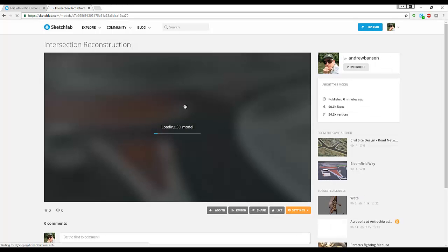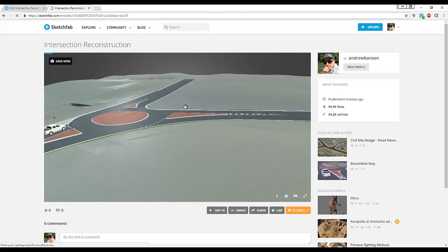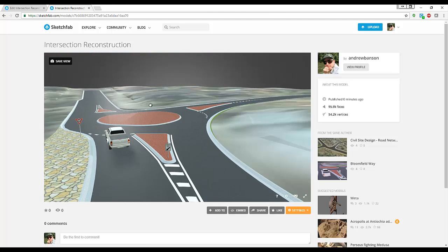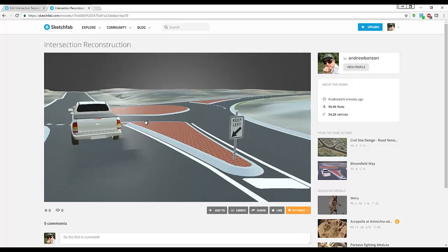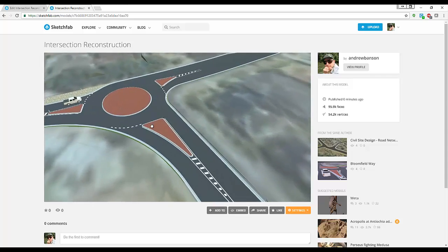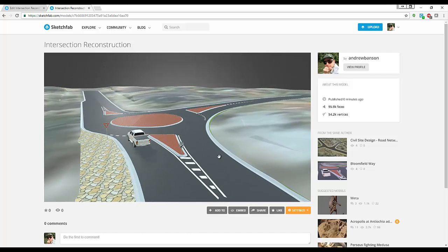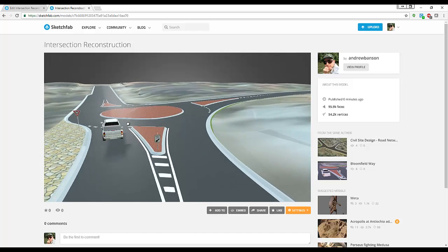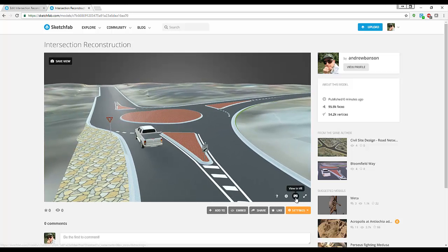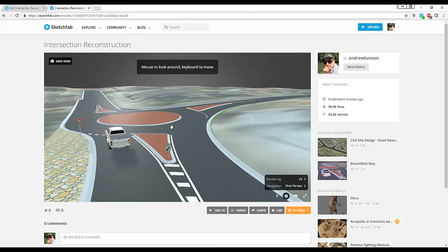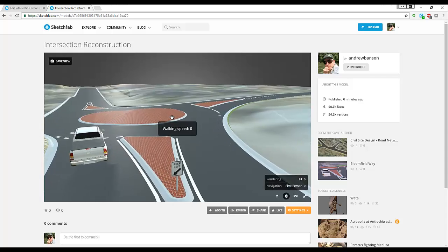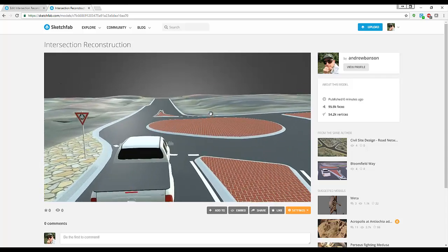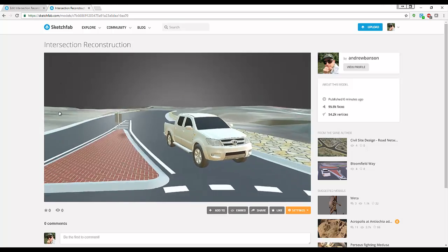Okay, so this is a page that people will see. Right, when the model loads up, it zooms to that location, and basically with the mouse we can zoom and pan and rotate. You can do this on lots of different devices. I've done it on my phone and tablet, and there is actually a VR mode, so if you've got a VR headset, you can go into VR mode as well. In the settings, rather than orbiting, you can go to first person mode, so you can change the walk speed, maybe slow it down a bit, and using the arrows on my keyboard I can zoom around, walk around as if I was in a computer game, which is pretty cool.